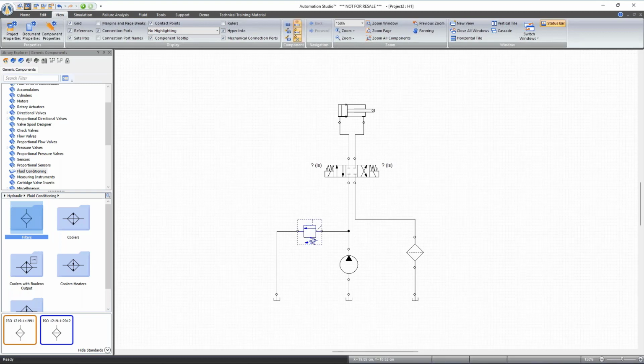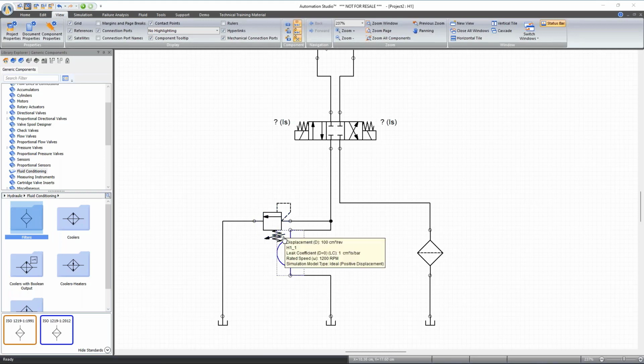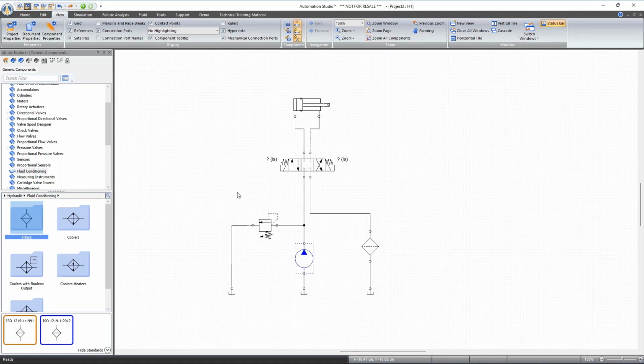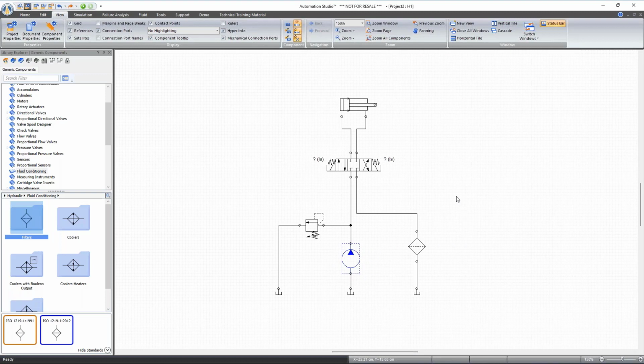With the Shift key, we will also be able to perform a multi-selection over a bunch of components. Let's say you have some components that are close together. Sometimes it's difficult to select the right one, so the Shift key will toggle between components that may be a bit overlapped. Okay, so this is about the basic manipulation using the Shift and Control keys.